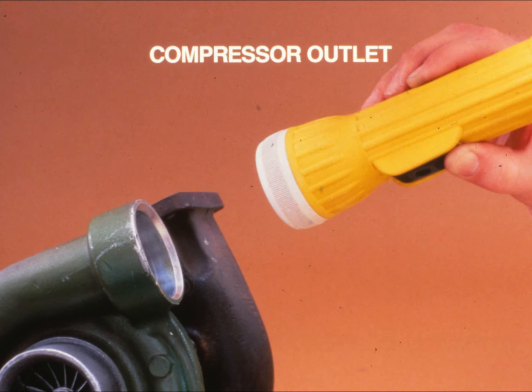The second inspection is the compressor housing outlet. The outlet should be clean and no oil or dirt should be present. Mark it on your checklist if oil or dirt is found.